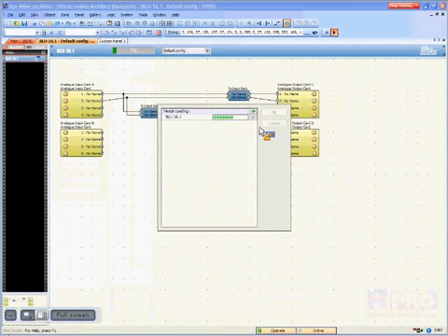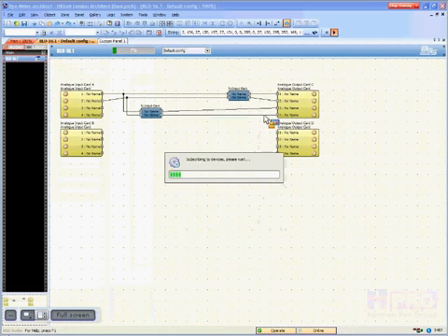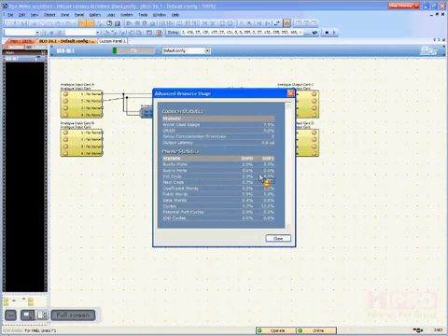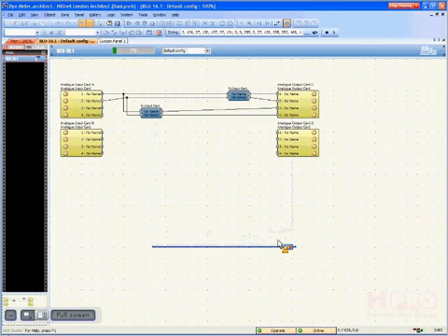Back online, have to reload because I have to load it without the meters turned on. And instead of being at 19.3%, now I'm at 7.9%. So those other 18 meters took almost 12%. Now I have 2 dynamic meters. So there's the first one that pops up. I pop a second one up, pin it in place, hover over a wire somewhere else, nothing happens. I'm only allowed 2 at a time because that's what I have set under properties.